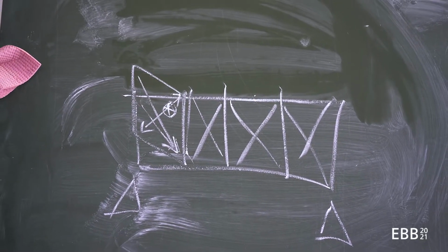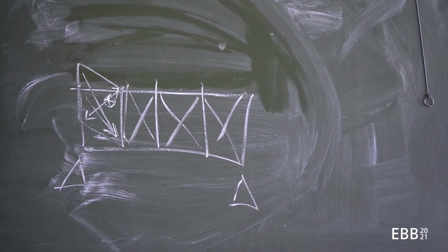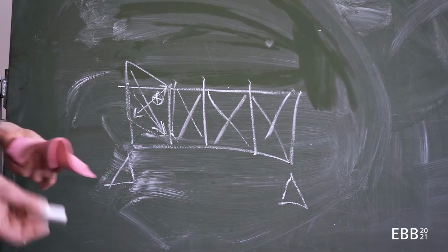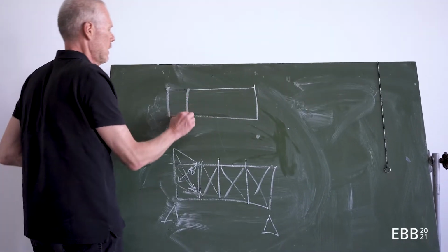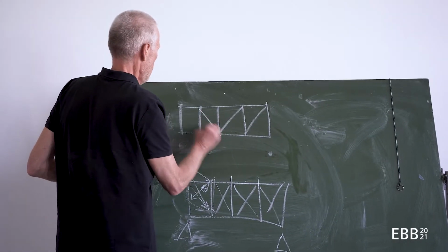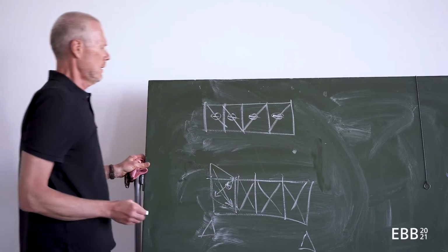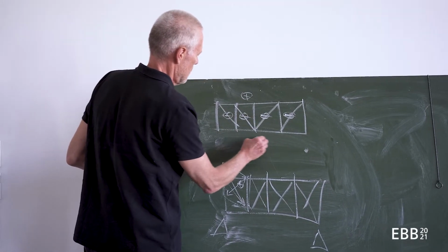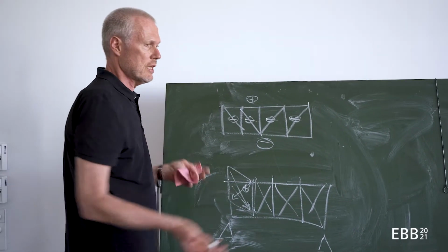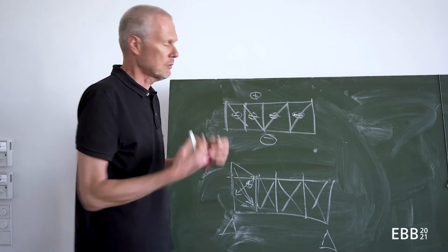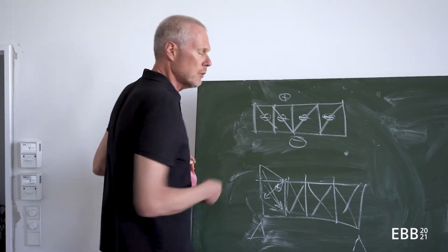compression. So if I have a material where the linkage can be done easily, I would try to put the diagonal in tension, as the danger of buckling is lower than in the other case. So for a steel truss, this would mean that the diagonals should be falling to the middle, so that they would always be charged in tension. Upper part being in compression, the lower part being in tension, and the diagonals, as we have seen here, would then be charged in tension as well, so I can make them thinner. For example, with a narrower rod or with a cable, than the other way around.